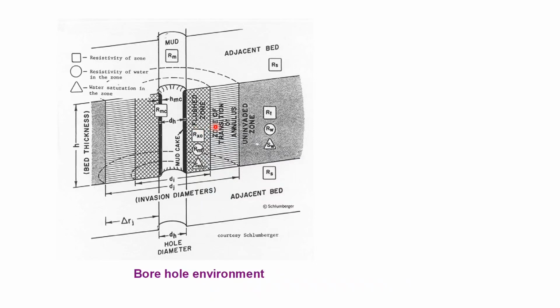The presence of mineral deposits may also decrease the hole diameter, or they may also increase the casing. Any change in the nature or thickness of the material between the logging sensor, that is the probe, and the rock will be affected because of the mud cake. So we should be very careful while finding the diameter of the borehole and the changes in the borehole by using a caliper log. And we'll go for the final thing, the effects of drilling on the logs.